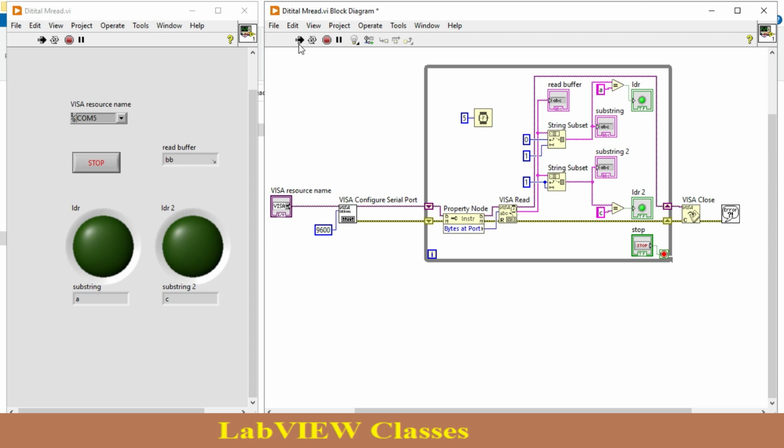So in this case, when you are just reading the data, it is very important you just put delay also. Right now I am just putting a delay of only 5 milliseconds. You need to put delay. I am just showing you when you do not put a delay and when you put a delay, what is the difference. So right now I just put the delay. So right now I just put my hand over this pin. Let's check the data is changing or not.